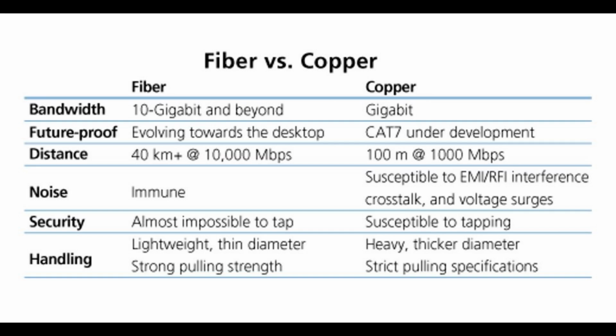2. Buffer coating. Protective layer: each optical fiber is surrounded by a buffer coating, which serves as a protective layer. This coating helps prevent damage to the delicate fibers during handling, installation, and use. 3. Strength members. Reinforcement: fiber optic cables often include strength members, such as aramid yarn or fiberglass, to provide tensile strength and protect the fibers from stretching or breaking. 4. Outer jacket. Protective cover: the entire cable is encased in an outer jacket, which provides additional protection against environmental factors like moisture, chemicals, and physical damage.